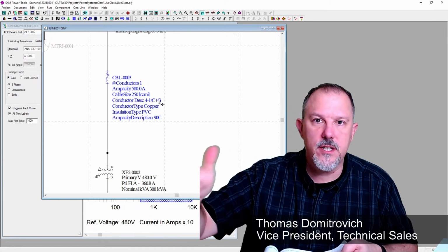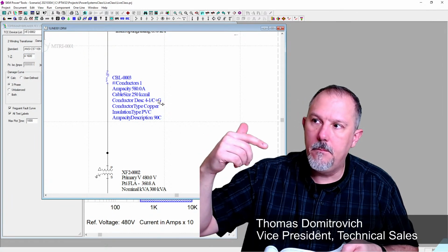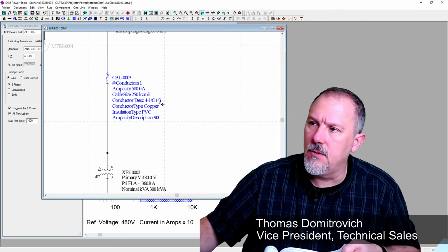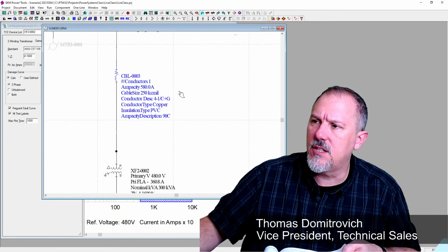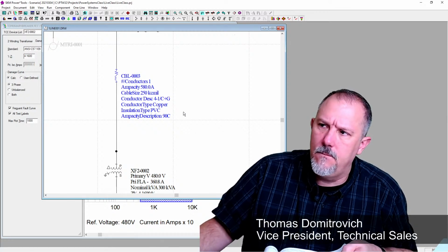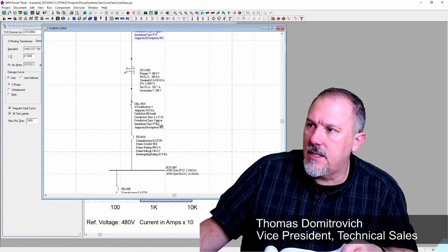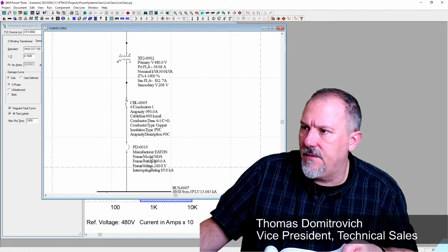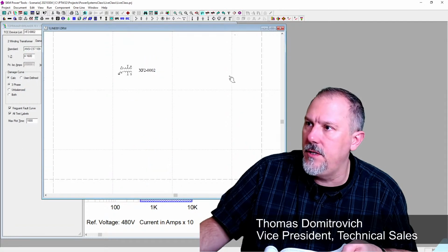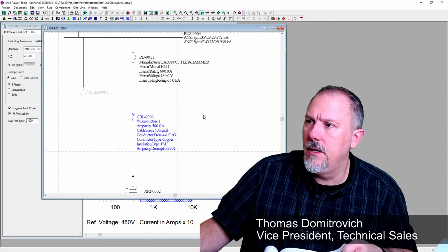I've already adjusted for my overcurrent protective device. If ambient temperatures, I'm not going to deal with that, but you can deal with that yourself, making your adjustments there. What else would impact the size of this conductor? I don't think anything else. So that conductor looks good. This conductor is, I've got 800 amps, and how many do I have? 2, so I'm good. Just make sure how many I have up here. I've got 2, I'm good.